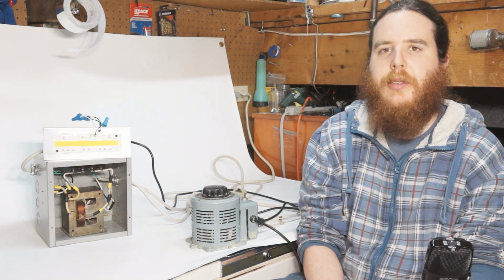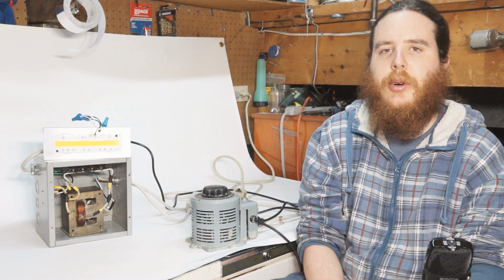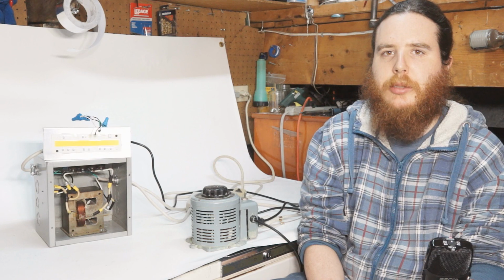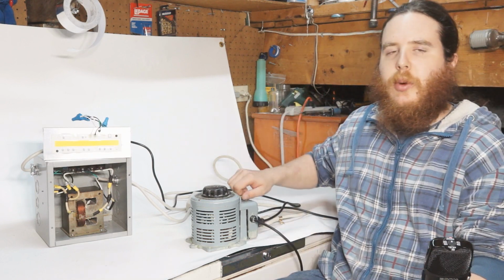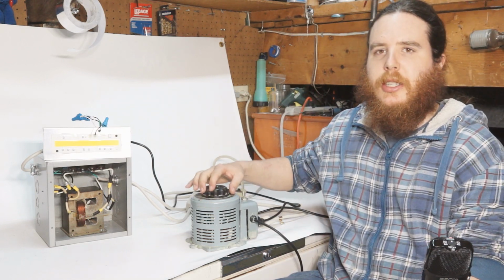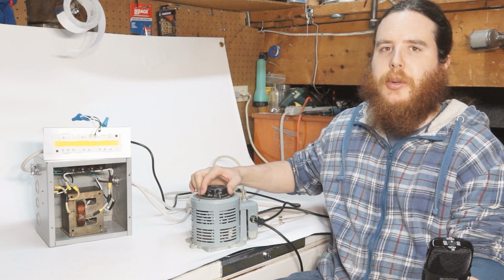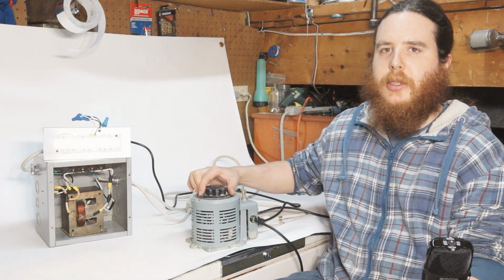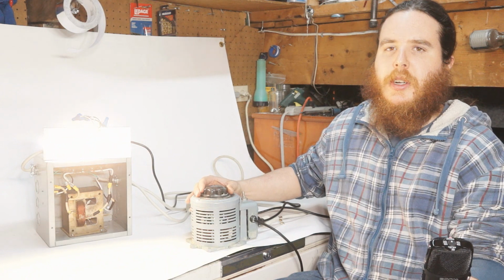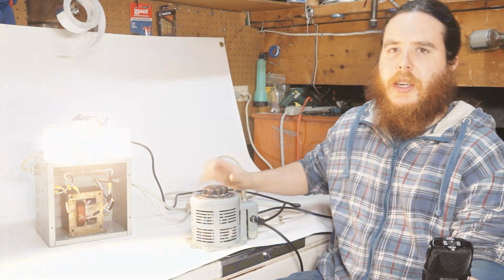However, LEDs all have a minimum forward voltage. This is the voltage below which no current flows, and therefore no light is produced. You can see as I gradually increase the voltage applied to these LEDs, nothing happens until we hit that certain minimum voltage. Above this voltage, current can flow through the LEDs and light is produced.